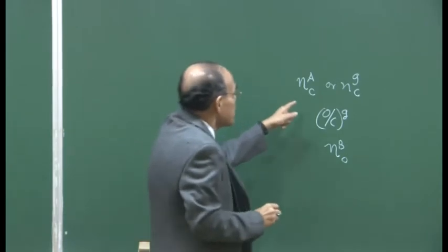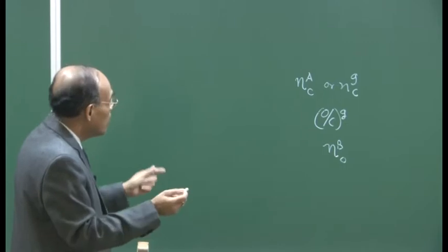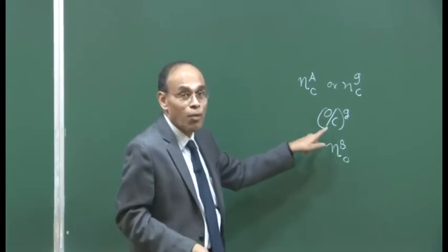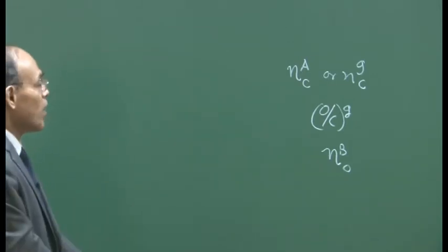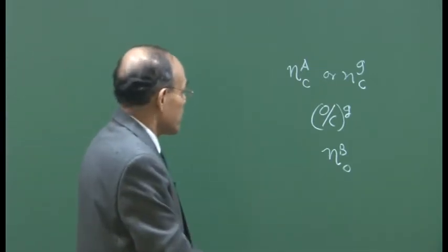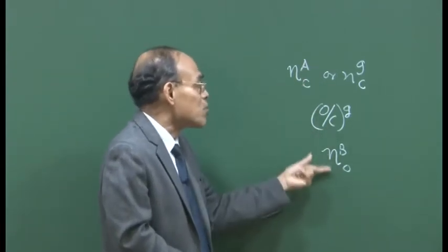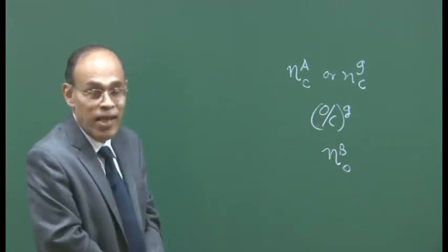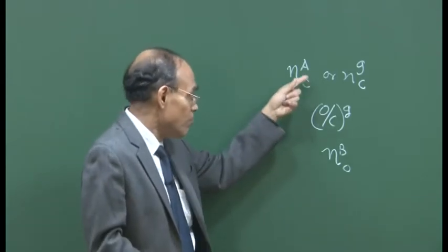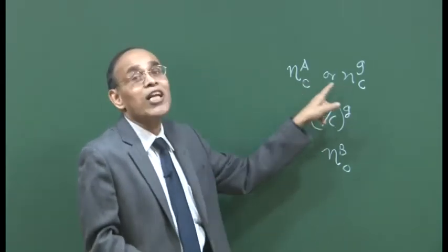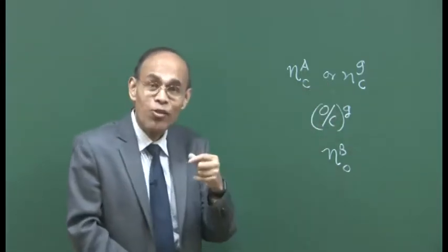So if these 3 parameters can be given to us, if we can calculate, then we should have the coke rate, we should have the top gas composition, we should have the blast rate, or how much blast will be needed under steady state operation. This essentially tells us that we need 3 equations to calculate these 3 variables. So these are now my model parameters, or the key blast furnace operating parameters, and these can be calculated on the basis of 3 equations.